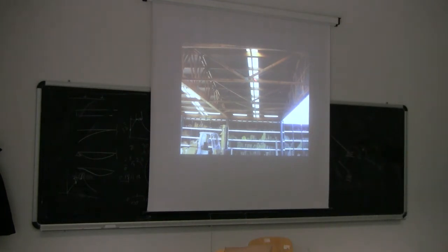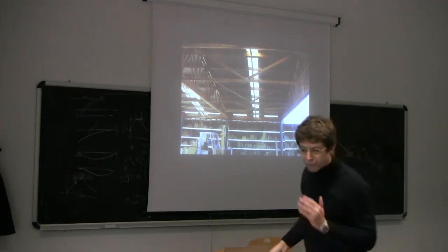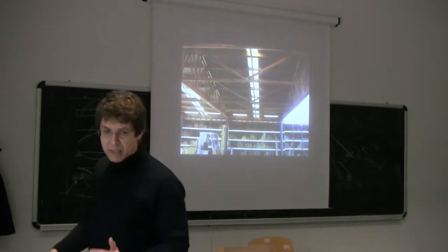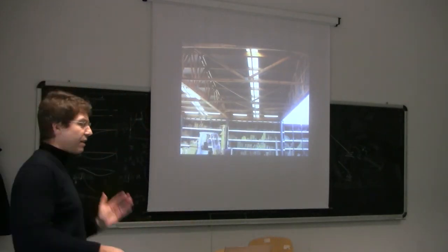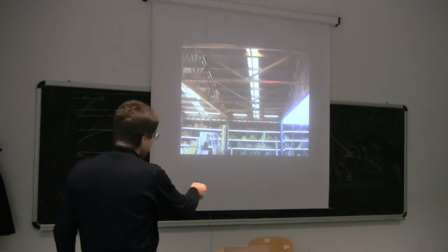And the meaning of those perpendicular trusses again is to restrain laterally the top chord and the bottom chord, to avoid that the top chord and the bottom chord may deflect laterally and may rotate torsionally. Again, remember that for this kind of structure, the major problem in terms of buckling is out-of-plane buckling, which means lateral torsional buckling. In order to avoid lateral torsional buckling, we need to provide some restraint.